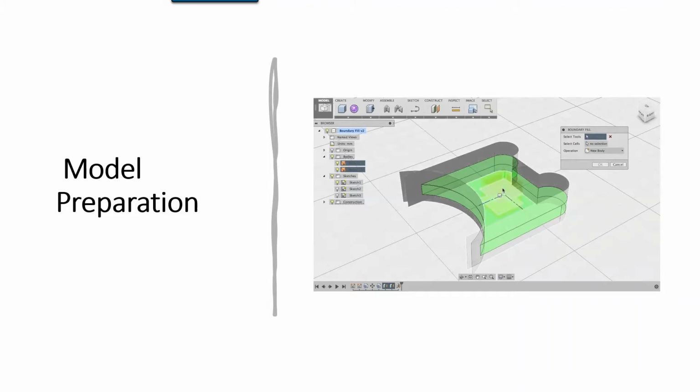If they send you surfaces, a good technique you can use is the boundary fill operation. Obviously, you can also do some surfacing strategies. You can make sure that you have a watertight seal and then stitch up these surfaces, and that's going to create a solid body. So many different ways to go about it. But boundary fill is one of those useful techniques that's just good to know and be familiar with.